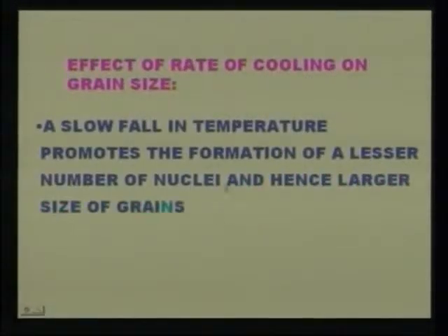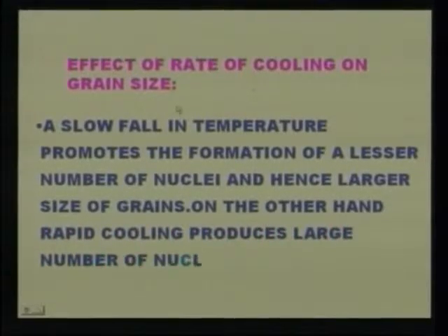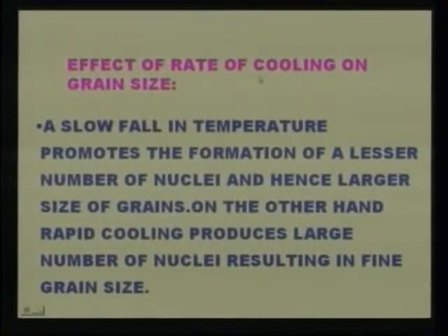Now let us see the effect of rate of cooling on grain size. Now what is the effect of cooling? A slow fall in temperature promotes the formation of a lesser number of nuclei and hence larger size of grains. On the other hand, rapid cooling produces a larger number of nuclei resulting in fine grain size.